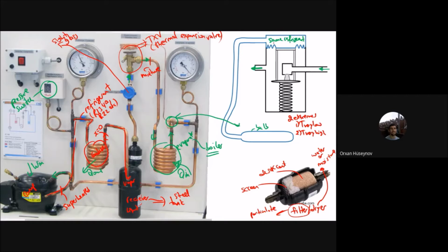As the pressure increases, you will have the compression, so that the pressure will apply some force on this component here. As it applies the force, it will compress the piston, that spring here. As it compresses the spring, you can see that this part, this outlet will open. Okay, this outlet will open, and you will have more refrigerant into the system. And when the temperature is very high, you will have more mass flow rate.